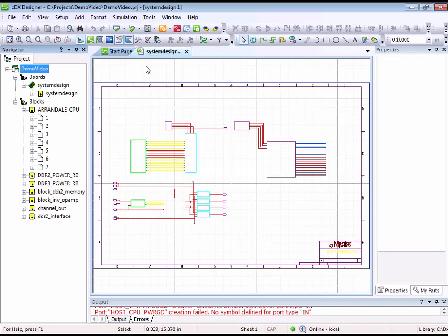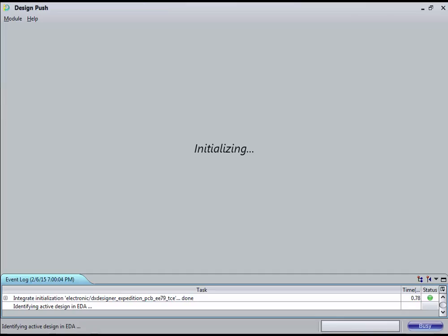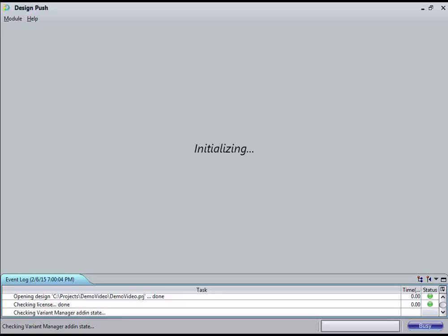Up to now, there are still no elements existing in our PLM system. To push the design into the PLM system, the module save is used. Also, PCB fabrication and assembly data can be created and uploaded, and the bill of materials be transferred with the save module.